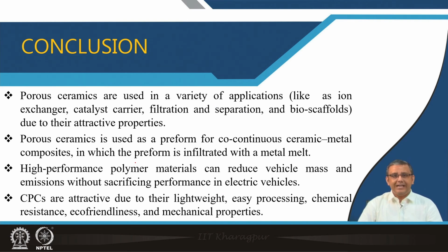In this lecture we have shown many applications of both porous ceramics and polymer foams. We have seen that porous ceramics are used for many applications because of their attractive properties, like high melting point, which gives high temperature resistance, good strength and stiffness, and high hardness, which provides high wear resistance, and the combination with a high amount of porosity, which provides a good surface area. These porous ceramics are very attractive materials for ion exchangers, catalyst carriers, filtration and separation, bioscaffolds and so on.